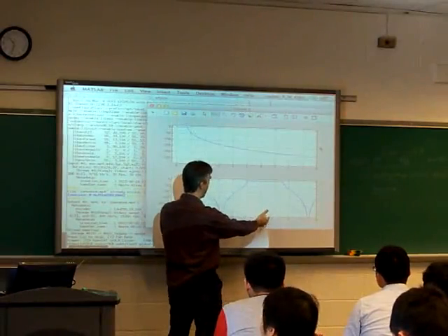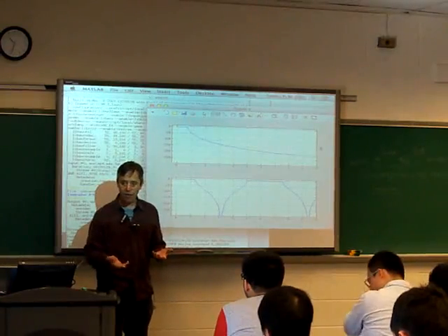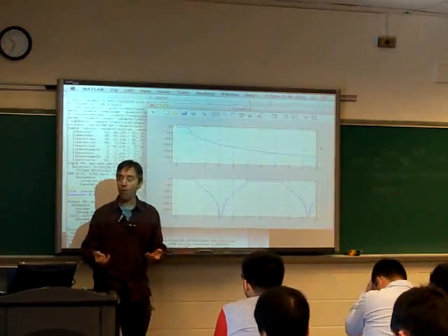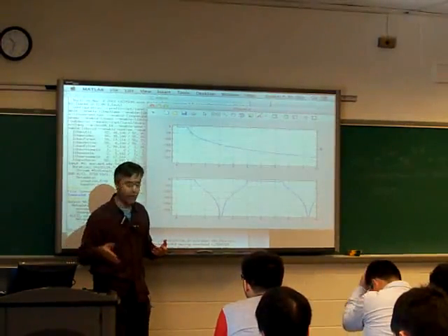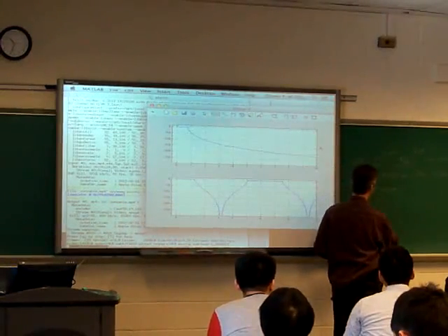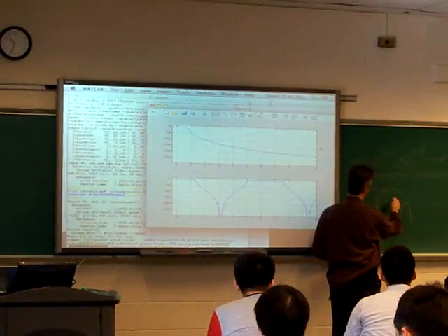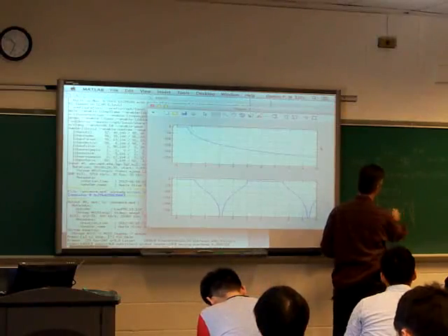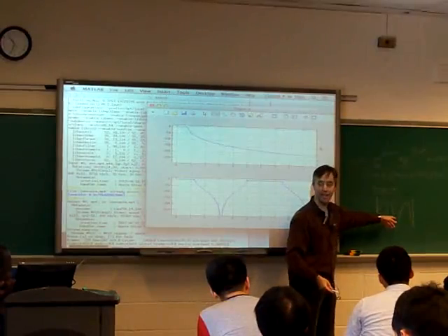These frequencies up here correspond to frequencies where if they were pure sinusoids, they'd be completing more than one half cycle every sampling interval, which basically means we've got a sinusoid that looks something like this, but then we're taking samples where there's more than half a cycle of the sinusoid before we get to the next sample.